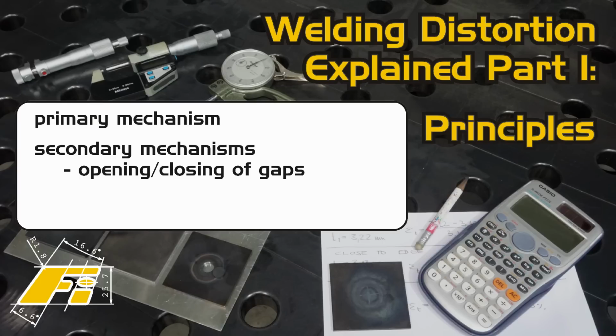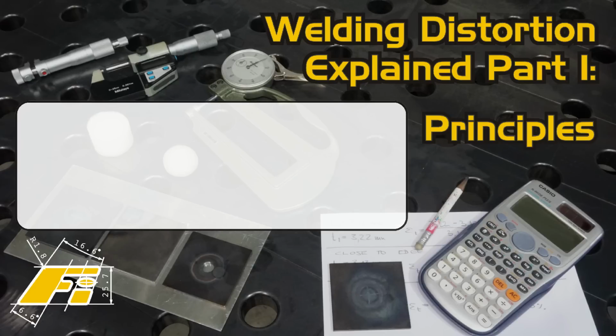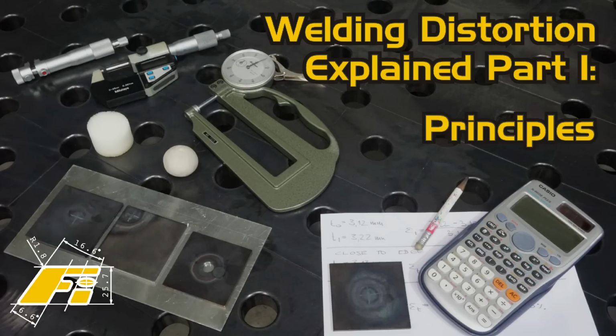The primary mechanism of welding distortion is found more or less pronounced in all ductile, that is, formable metals. In these materials, qualitatively we always find the same behavior of distortion. We encounter it not only during welding, but also during quenching with heat treatments, for example hardening or precipitation hardening, or we find it in additive manufacturing.